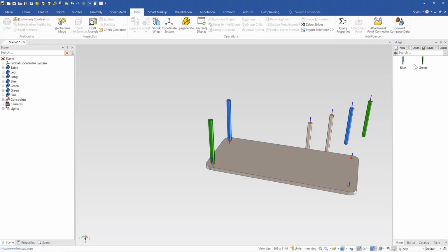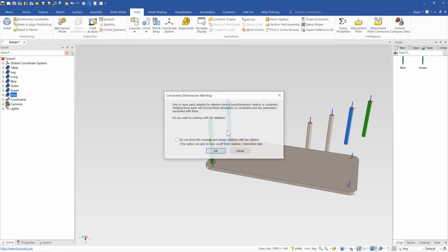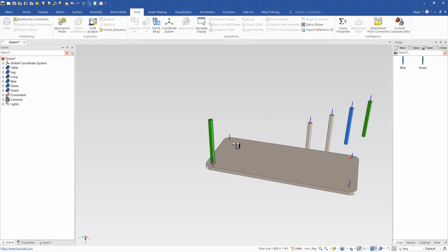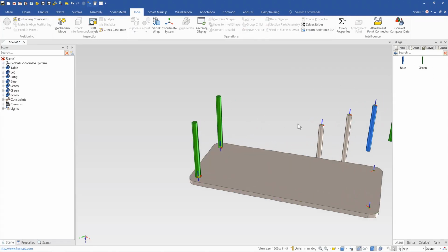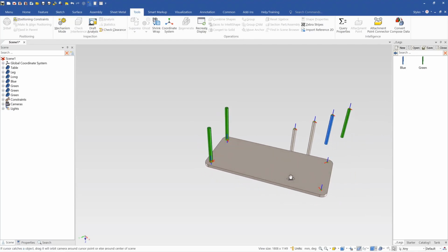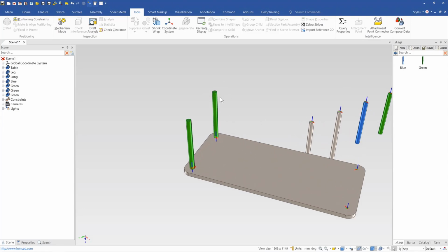Again, if you want to drop individually, you can still change that behavior just by dropping individually. Like if we drop a green here, it will still be a green because we're actually dropping from inside the group like that. But that's a very nice way to automate the behavior of different items attaching. For example, if you have different feet going onto an item, based on if the item is round or square, you can have square feet or round feet, just based on those catalog references, which basically tell the item what it wants from that catalog group, what item it wants from that group.